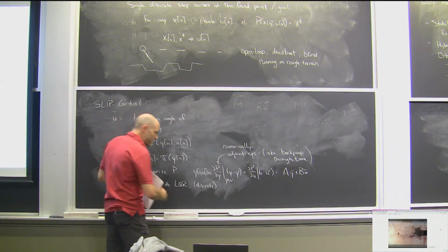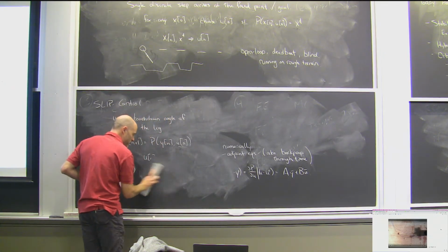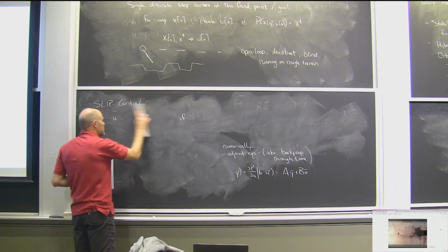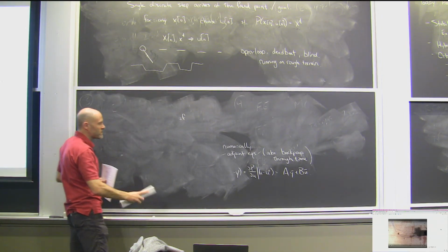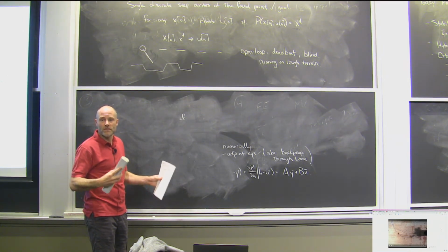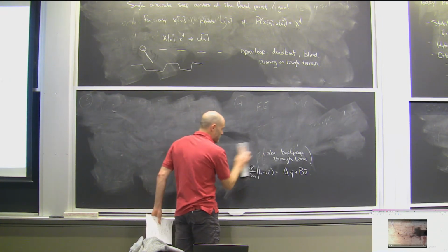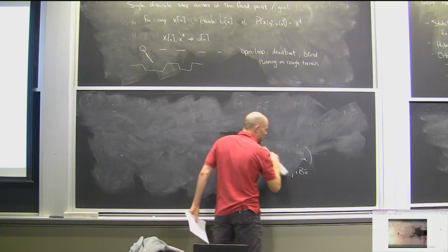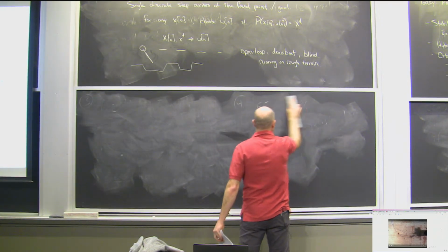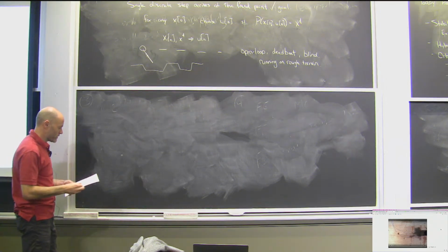And I should say that I lean heavily on LQR in these lectures because it's the one we talked about. I would almost be happier calling it linear optimal control, right? Most of these things are not particular to LQR, but they are particular to the notion of trying to reason about the local linear dynamics of the system and then doing something that we know how to do well from the class of linear optimal control. So the same thing's true here. I'll do LQR because we know it.